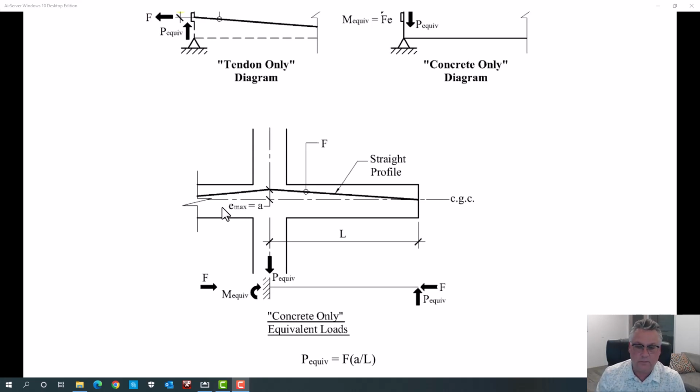In concrete, we're cast in place. We may want to be level after level after level of doing the same thing. Wood, that would kind of fall apart in that situation. It's not easy to make wood cantilever on a regular basis vertically up a building. In steel, it usually means a lot of welding. So there's a real premium or expense in steel or wood.